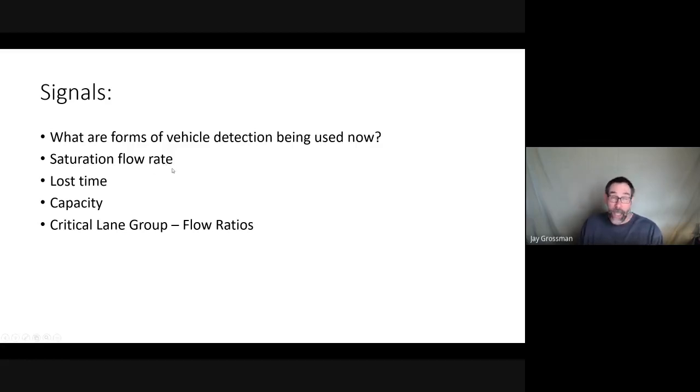If I tell you what the headway is, right? If it's 2 seconds between vehicles, you should be able to calculate what the saturation flow rate is. If I tell you the saturation headway is 2 seconds per vehicle, then you should be able to back calculate what the flow rate is from that.